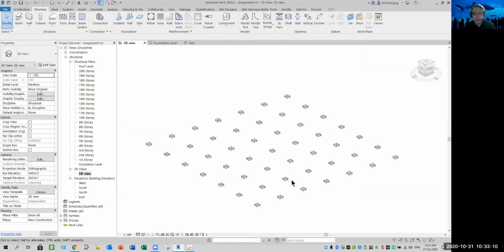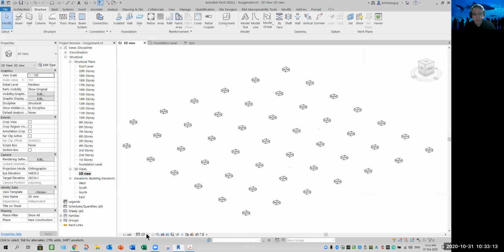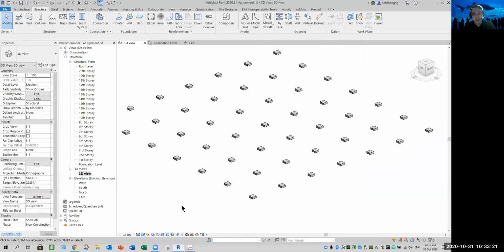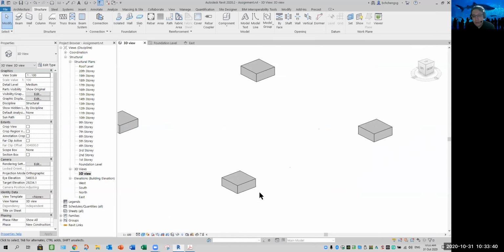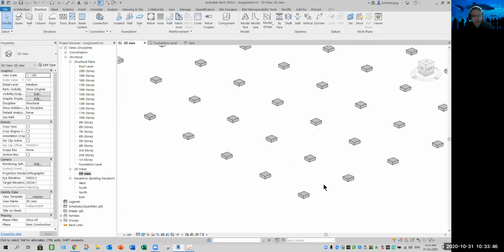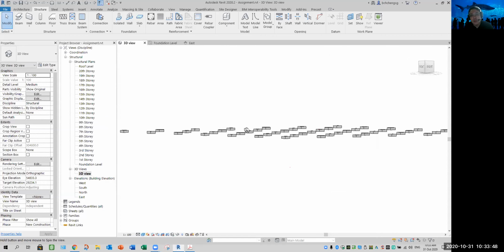So what I want is not to see wireframe, it should see them in shaded or consistent color. Shaded means there are some dark faces. That means it's telling you there's a sun casting from one direction. But if you are doing conceptual, meantime, I want to set it as consistent color, which is lights are everywhere. So you won't miss out anything. See, every component is nicely brightened, irrespective of how you orbit. See that? There's no dark face at all.